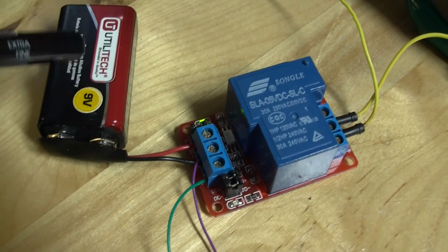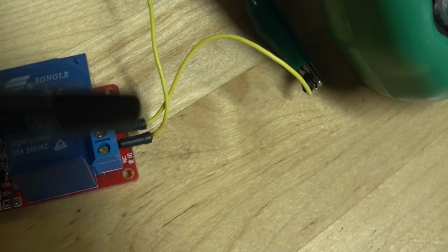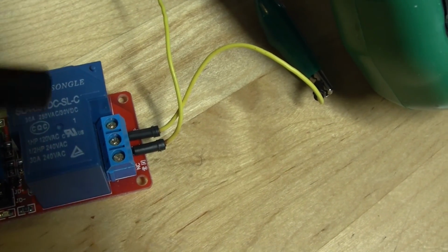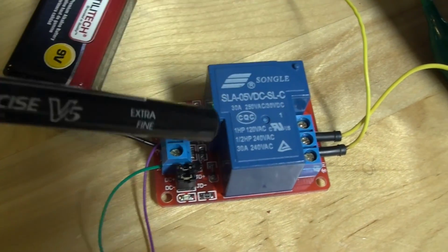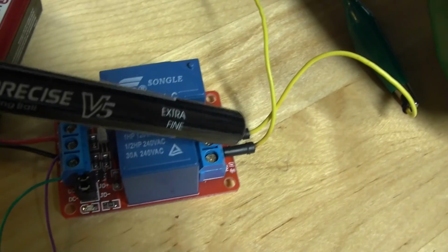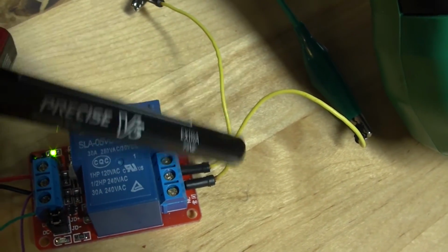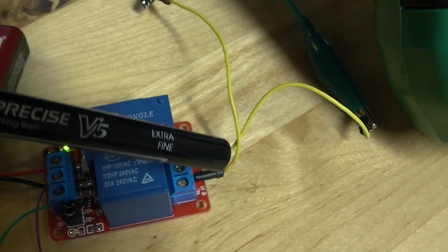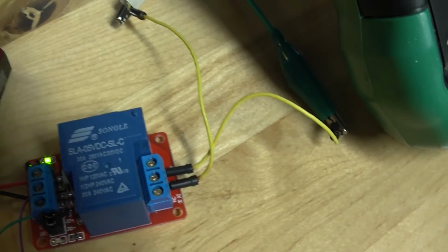So this is a typical 9-volt battery pack. The other end of the switch has normally open, normally closed, and a common port. So basically, I'll explain that in a few seconds here. But basically, what that does is when the relay switch engages itself, we want this end of the wires to be connected mechanically, so to speak. So when they are connected, the circuit is closed. When the circuit is closed, the radio is powered up, and when the circuit is open, the radio is switched off, obviously.